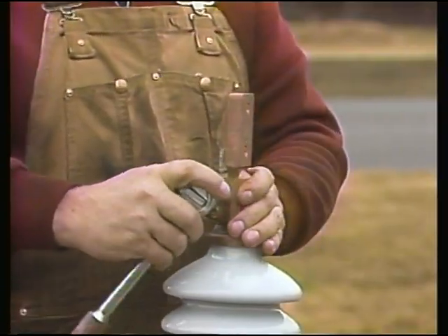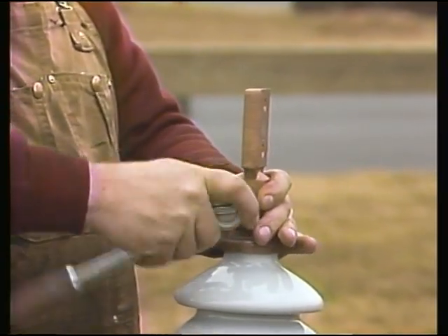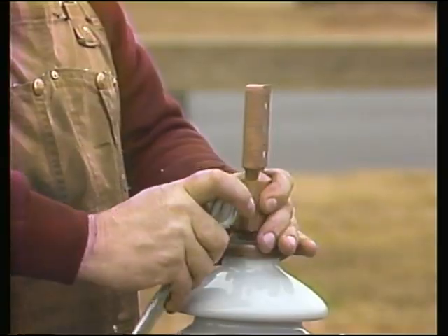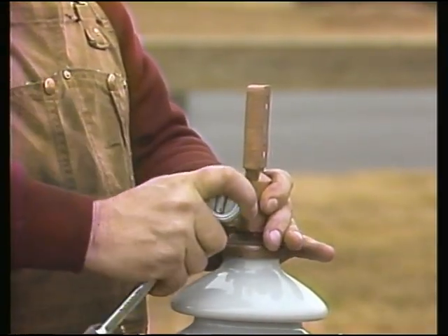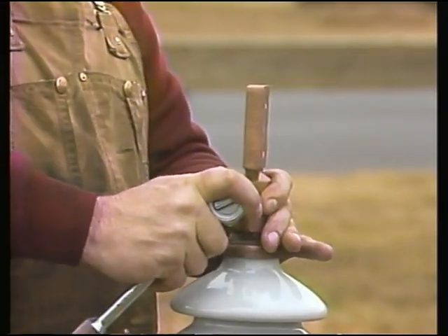To connect the termination to other electrical equipment, a fitting called an aerial lug is used. An aerial lug screws onto the threads of the connector and is held in place by 2 bolts. So, as you can see, a termination on a PILC cable is quite different from the other terminations we've seen.